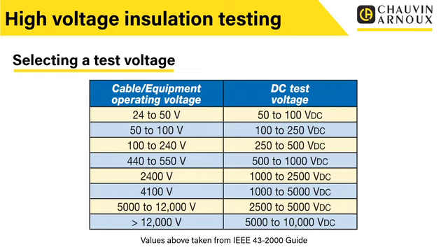So you can see on here for typical circuits, our 230 volts main circuits, for example, we would generally test somewhere between 250 and 500 volts, and a 500 volt insulation resistance test, as we talked about last time, is very common. But as the circuits start to go up, that's where we need to start using the higher voltages to actually get some information. And we'll also talk about, as we go on, step voltage testing. And step voltage testing, again, uses that difference in test voltage, that increased test voltage, to actually tell us about the condition of the insulation.